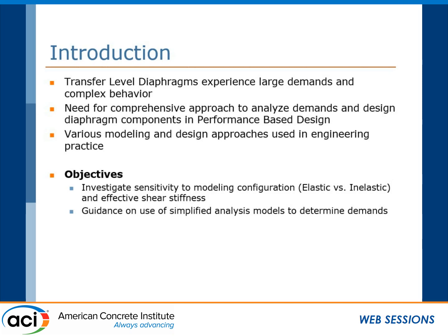So one of the objectives is to look into the sensitivity of the demands when you model a transfer level diaphragm as linear elastic versus modeling it as a nonlinear diaphragm. Another objective is to compare forces obtained from a finite element analysis to more simplified methods, such as analyzing the diaphragms as a rigid beam with rigid supports. The software we used for this study was Perform 3D, as standard, something normally used in regular practice.